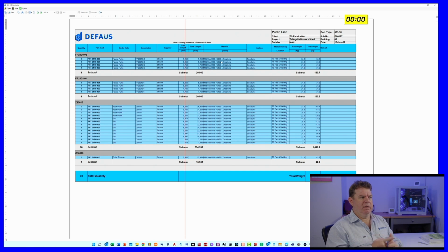You need to know what sort of material it is, so mild steel, what grade of mild steel it is, and what finish, because some of these steel products will come in black, they might come pre-painted, Duragal, some might come hot dip galvanized, some have special coatings that you order, like even with aluminium products you might have a mill finish or a polished or a semi-polished. That information is contained in the material list, and then the coating might be a powder coating secondary phase to that.